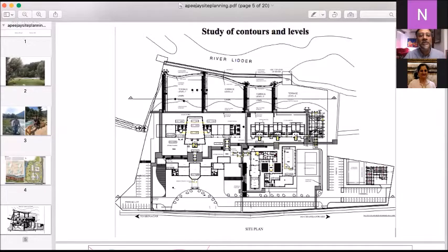If you see, this is where the gate is, where my mouse is right now. We created a slightly VIP parking on this side, extreme left, on the right, and then further on the right, more parking. So this was the basic site plan, which I explained with the contours, how we took care of the topography, because surface drainage is very, very important.